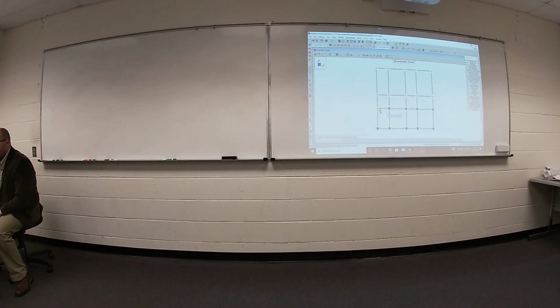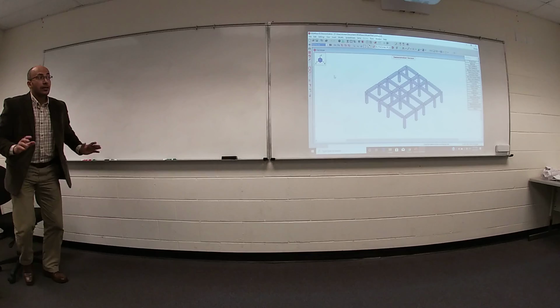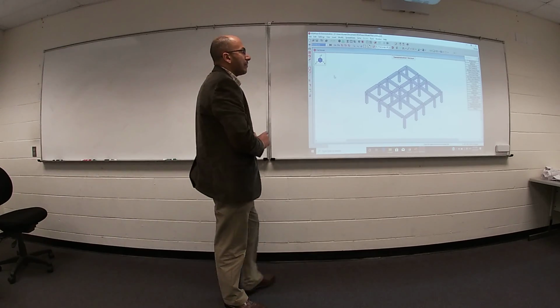I have a question. Do you know what is the height of each column? The elevation, correct? Yes, 10 feet, yes. Right now, I defined only your cross section. At the beginning, when you opened this model or this software, you defined the elevation, which was 10 feet. If you would like to check also, go ahead. I like each step to check everything before continuing. So go ahead, isometric, go ahead and choose full model. Yes, I'm good. Before continuing, check every step you did.